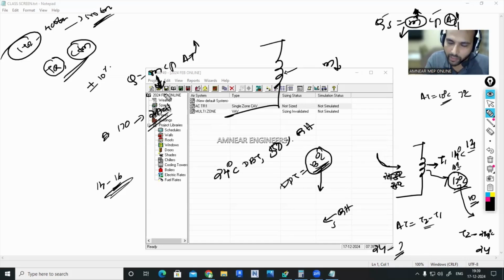to circulate the room air through the cooling coil. So initial cooling time will be more. So the AC machine will be consuming more electricity. Your electrical consumption will be more there. And also, if the supply temperature is not proper, an uneven stratification issue can come. Air temperature will not be uniformly distributed everywhere. A lot of issues can come.